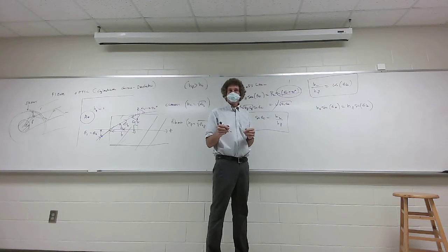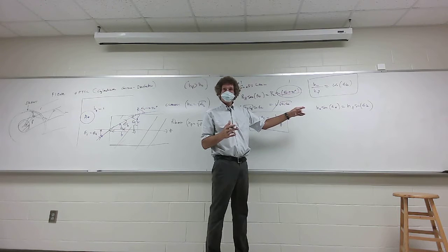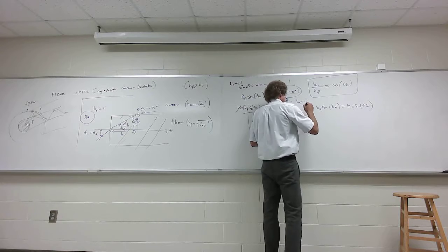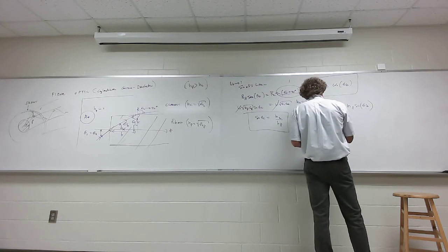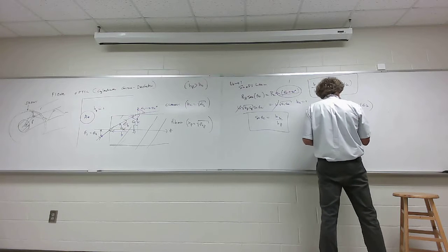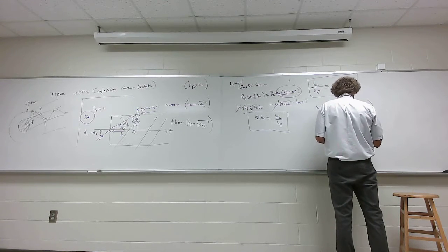Now here's the tricky use. There's probably a lot of different tricks. Y'all agree with that, by the way? I'm going to assume N A is 1. It's air. And that means the sine of theta A is equal to eta F, or the index of refraction of fiber, times the sine of theta B.